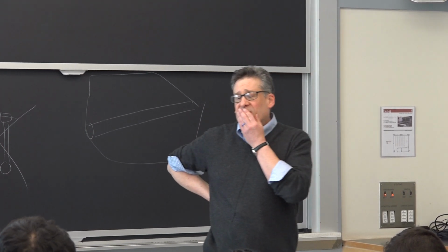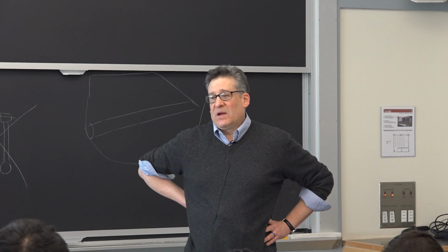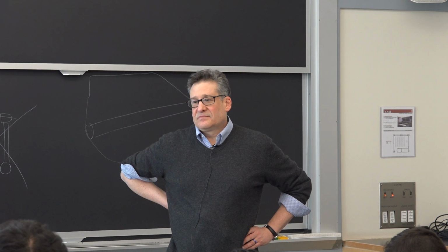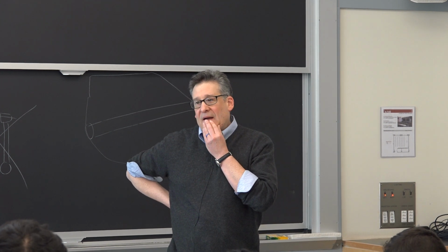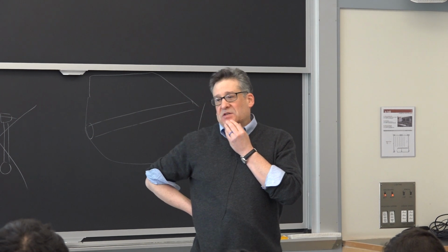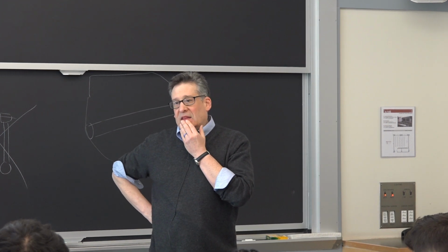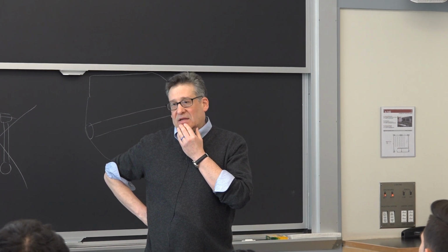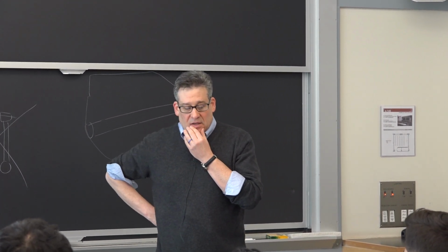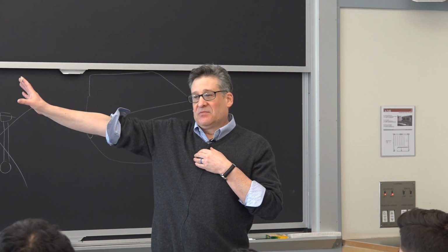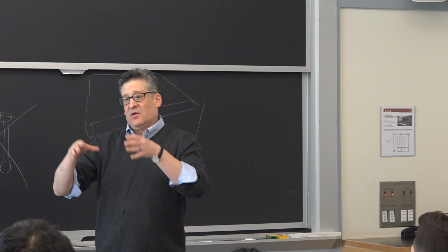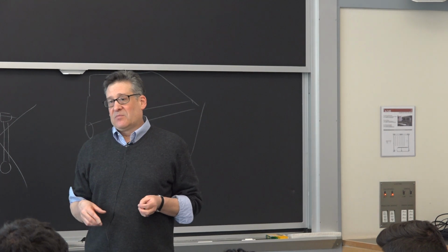Okay. Yeah, Kim. Some of them are to the power of 1/3. Maybe for just a straight ratio between the two. Do you just choose the design factor that gives you more, that has more of a failure? So those factors that you're talking about, the 1/3, the 1/2, that's related to the mode of loading, whether it's under bending, or torsion, or buckling. So you have to go ahead and then analyze. You have all these different tubes that make up the body structure, and you know that under certain loading conditions, they're under bending, they're under compression, they're under tensile, they're under buckling.